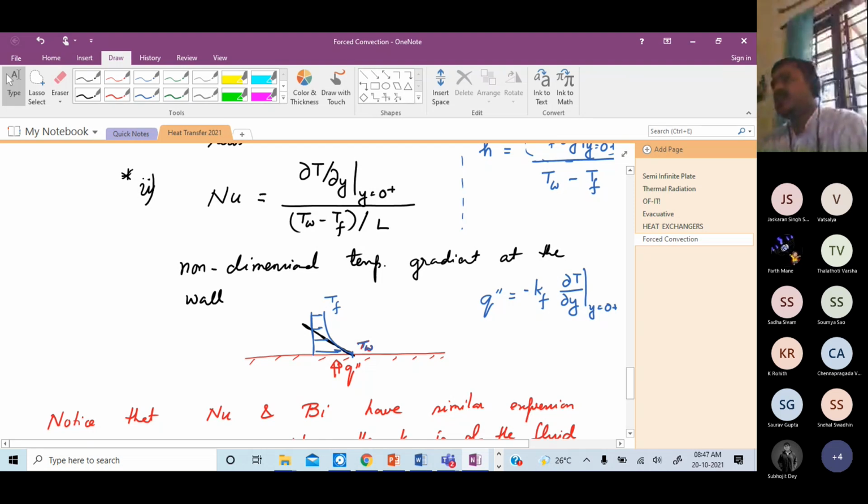And the first thing is, no, you cannot extend it. First of all, extending lumped capacitance to convection doesn't make sense, because they are completely unrelated. Lumped capacitance is for finding the temperature inside the solid, where it's purely conduction, and convection at the boundary.